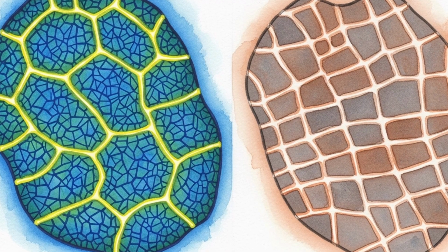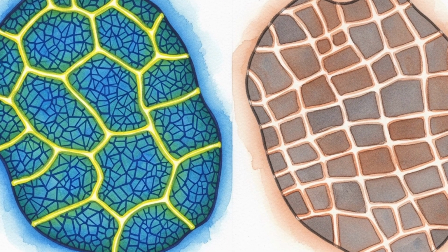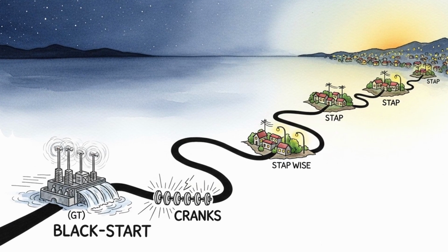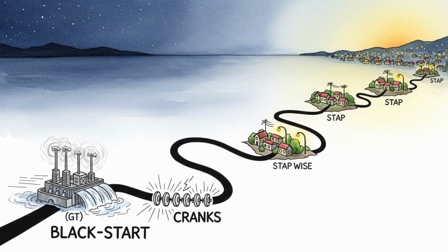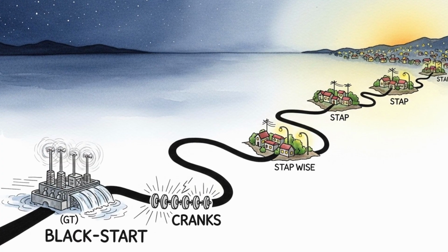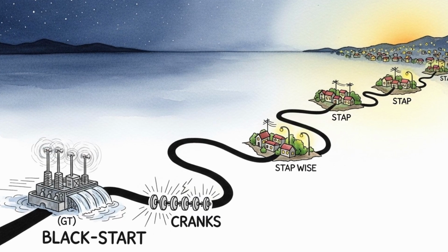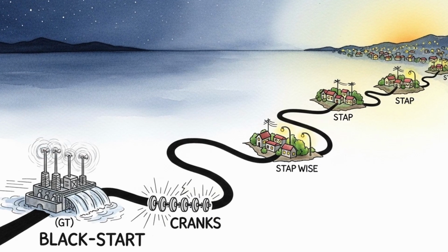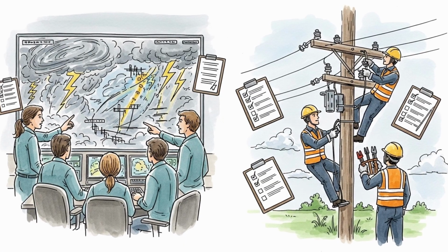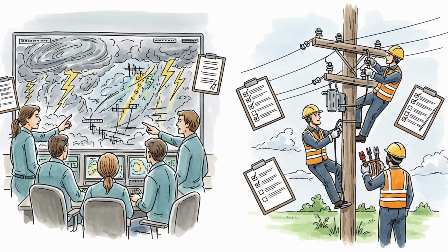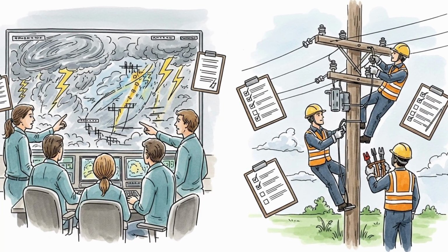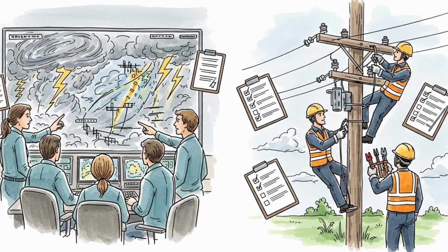Other long conductors experience different but related effects. Pipelines can see changes in cathodic protection currents, which alters corrosion control and can trigger alarms. Undersea telecommunication cables carry data on fiber, which is immune to induction, but the repeaters along the cable need power from conductive pairs. Those power feeds can experience geomagnetically induced voltages and currents, especially in long spans at high latitudes or near continental shelves. The storm evolves through phases.